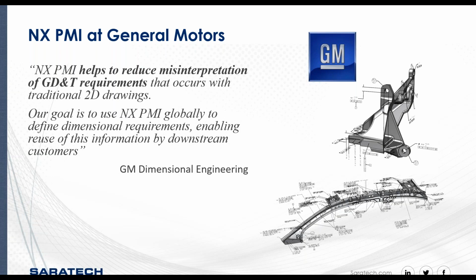So we talked about how you can use that PMI data applied to a 3D model and push that to your NC programming. So now, there's no misinterpretation on what surface this tolerance will be applied to, right? Or which holes, or what datum features are being called out. So things like this, it's easier once you have the model. You can fully interrogate what those tolerances are being applied to.